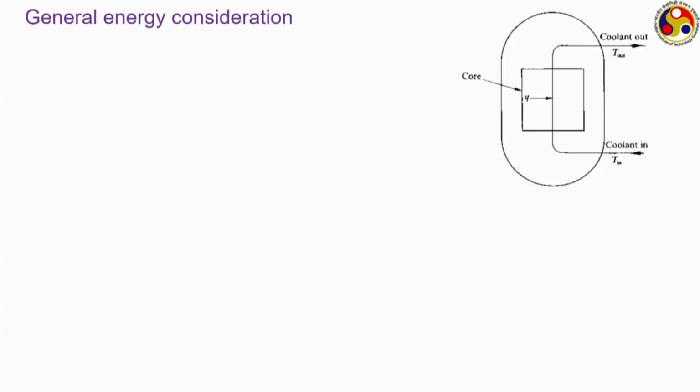So, once we know about the structure of the fuel, we are now ready to perform an energy analysis of a reactor or maybe just a single fuel element. We know that every fuel is covered by a jacket called cladding, and therefore, if we are particularly talking about a solid fuel, the energy produced inside the solid fuel will get conducted through the solid from its center line to the wall, and from the wall of the fuel the cladding is there. So, that heat has to be conducted through the cladding material as well, and then only will it be able to come in contact with the coolant.